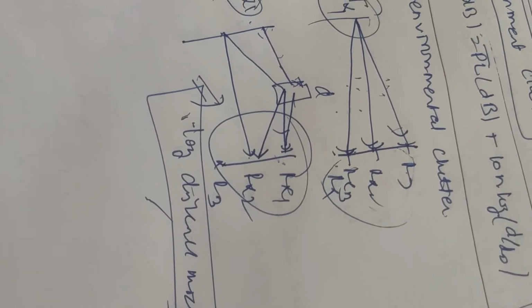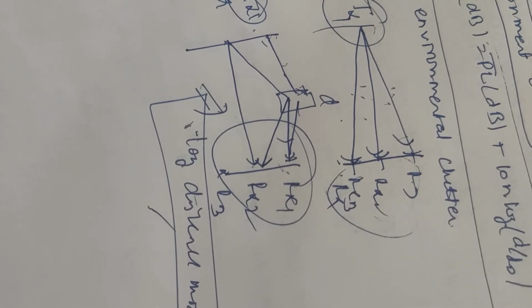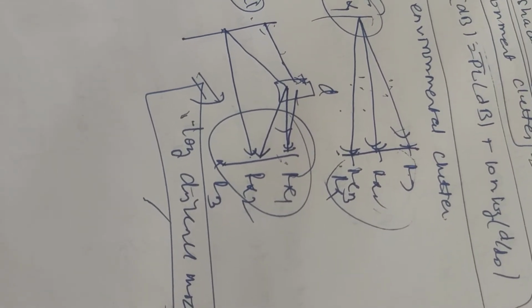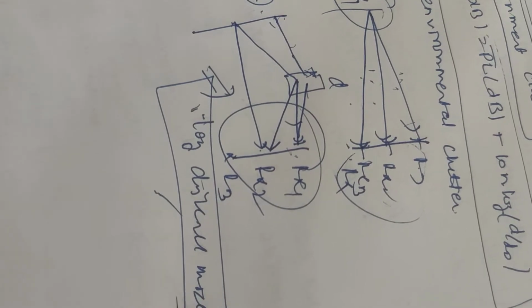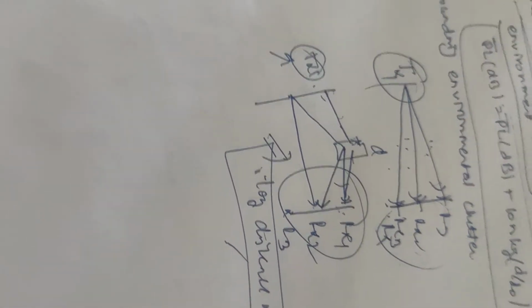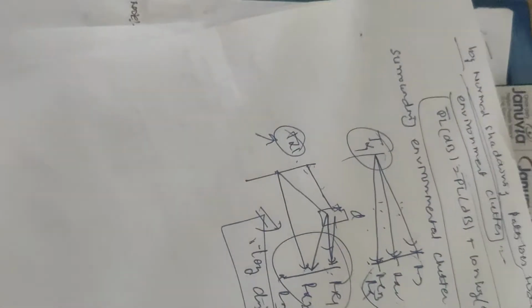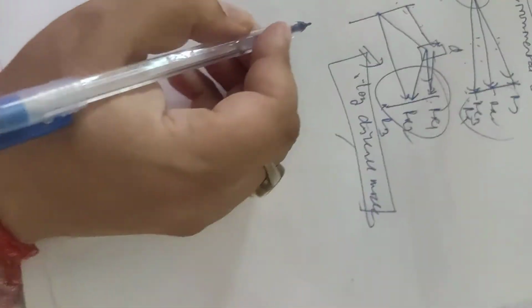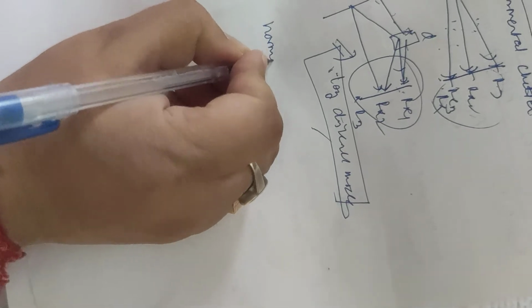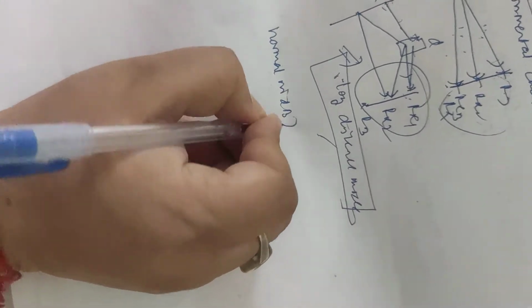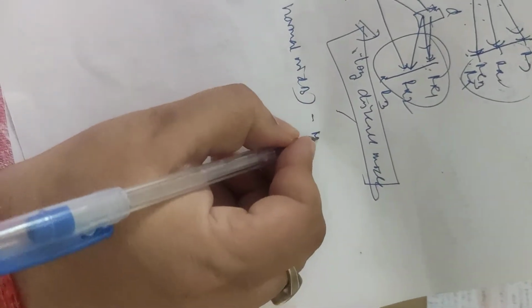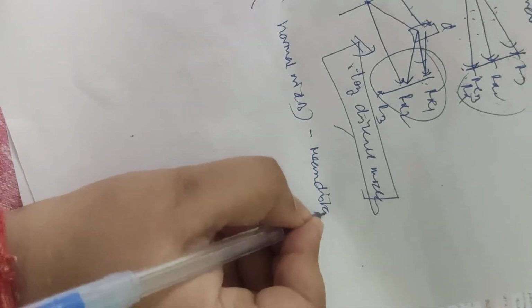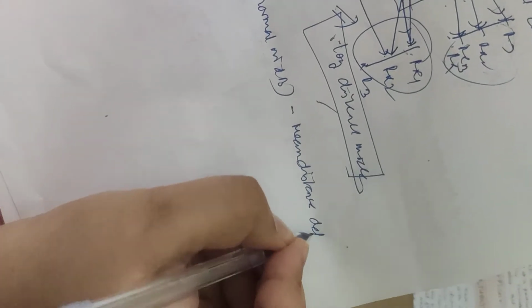measurements have shown that at any value of distance d, the path loss PL(d) at a particular location is random in nature and distributed log normally, that is, normal in dB, about the mean distance dependent value.